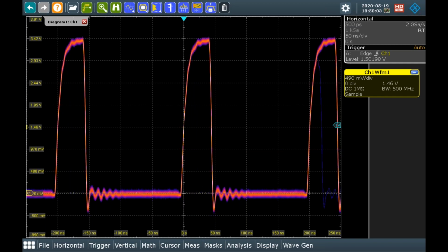So one of the common assumptions that people make when they're trying to debug a signal: if they're looking for a very rare event, something that's happening only a couple times per second, what we often see is people saying, oh, I'll get my highest bandwidth, fastest oscilloscope in the lab. The logic is understandable, it's usually the most expensive oscilloscope in the lab, but a lot of times those scopes were designed for a very particular job. They're trying to take that perfect single snapshot of an eye diagram. They're not trying to see all these dynamic changes.